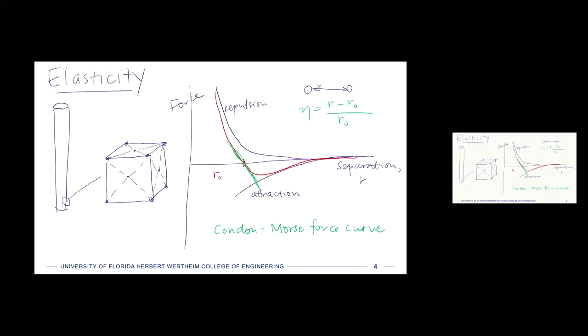And you will also recognize that that equation is identical to, I'm going to switch back to a different color here, our definition of engineering strain, which is epsilon is equal to whatever our deformed length of some dimension minus the initial length, that's supposed to say L naught, divided by L naught, right? So that's our definition of engineering strain.